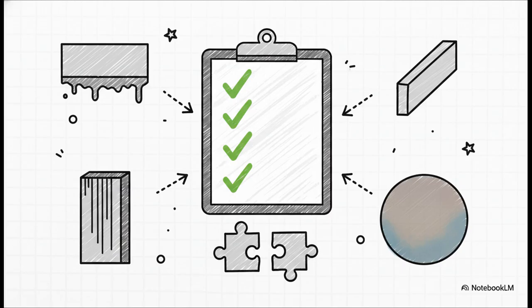Is the edge tapered instead of perfectly square? They used the wrong focal position. Seeing deep vertical striations? Their machine bed is vibrating. Notice significant discoloration from the heat-affected zone? They cooked the material by cutting way too slowly. And if your tabs and holes just flat out don't fit, their beam stability is terrible. Every single physical defect traces directly back to a technical variable they failed to control.